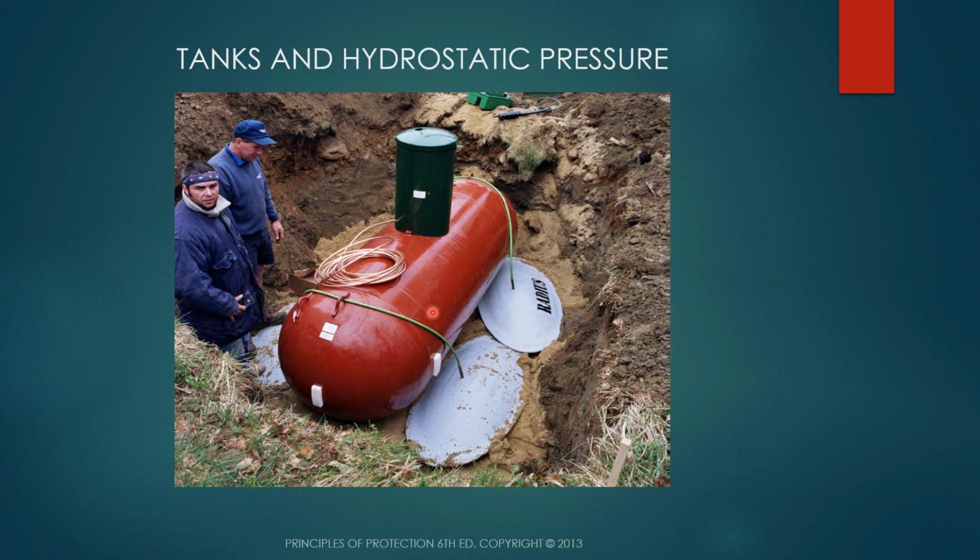So the counter hydrostatic pressure is by the weight of that propane in the bottom half of the tank. So you only have use of half the tank. That is insane. No other industry does that. So I had tie downs made up. These sit outside the footprint, and we have a 1.4 safety factor of hydrostatic counter buoyancy. So this worked well.